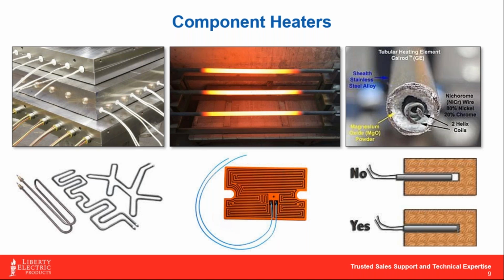And then of course, in the bottom right-hand picture, this is just a nice example that depicts you don't want to have an air gap whenever you're inserting a heater into a space. So if we consider our plenum in the upper left, if we have air gaps there, I like the design where they came out with the heater on the other tip, to know that it made it all the way through with no air gap.